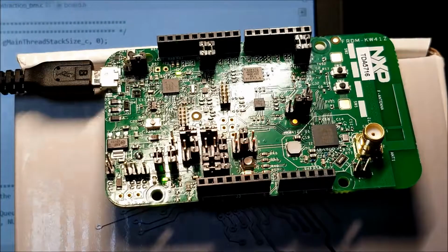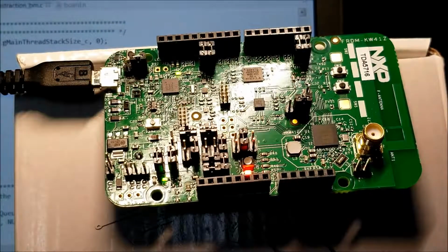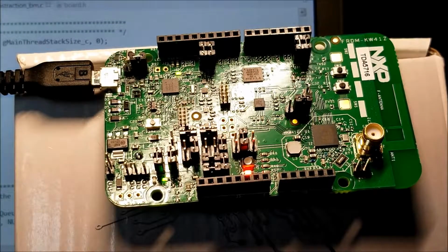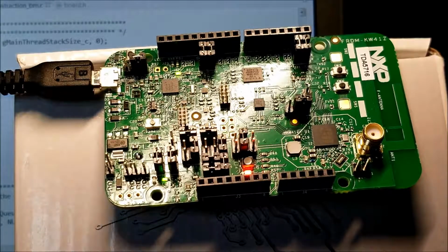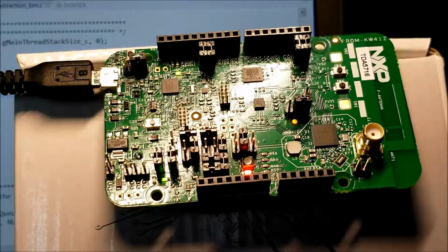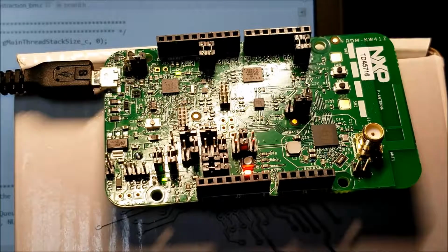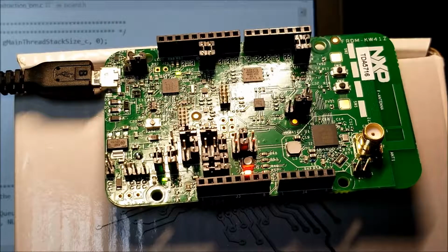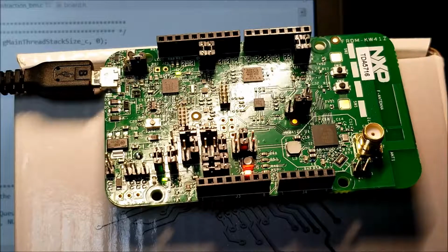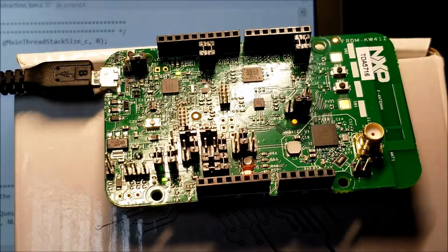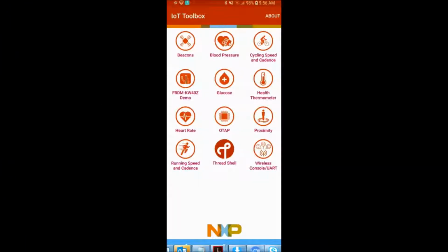My red square LED comes on. On my tablet, which is off screen, I start to do a scan. As soon as I make a connection, which I did, the red LED becomes solid, and now I can send commands from the tablet to the device, and with the terminal send device commands back. As soon as I disconnect, my red LED starts to blink again. And let's go back and see what it actually does with TeraTerm.